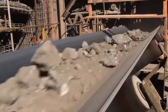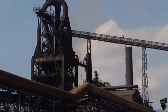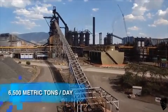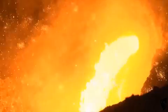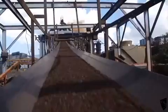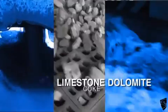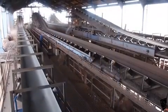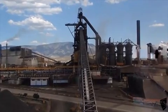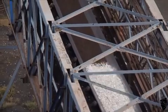Processed iron and coal, the basic raw materials for producing pig iron, are sent to blast furnaces consisting primarily of a large cylindrical structure over 160 feet high whose interior is lined with refractory brick. In the blast furnace, the iron oxides contained in the pellets and sinter, which are stored in the hopper's facility, along with limestone, dolomite, and coke, are reduced and converted to pig iron. Mixed in the proper amounts, these raw materials produce layers of various thicknesses when they are deposited in the blast furnaces through the charging system located on the top.